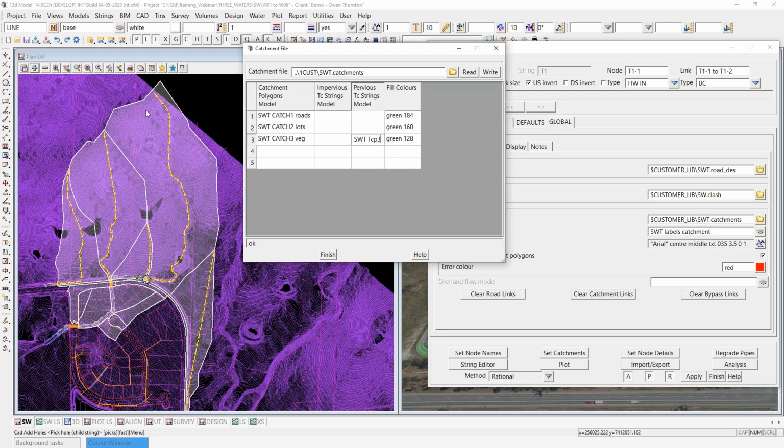Now, if you've never seen this arrowed line style before, this is actually the good old flow line style, but what you'll notice when version 14C2H finally gets released, this is a pre-release version that I'm running today, you will see a new line style in there for that flow line if you're used to using that flow line style. And this is now what it looks like. It's a little bit easier to see on screen. But the rules for catchments in the traverse model are identical. You still need to be careful of where you put vertex 1.